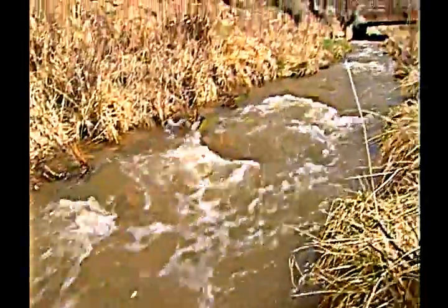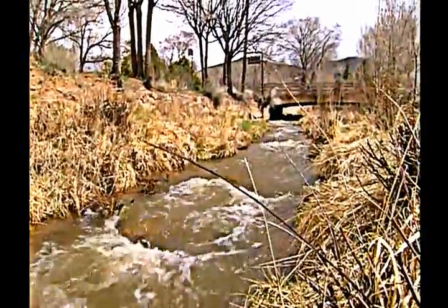Not all the particles that make up turbidity are a public health concern by themselves, but they can protect pathogens against disinfection. Naturally occurring particles, clay and other bits of dirt and stuff, can shield the pathogens from the disinfectant, making the disinfectant less likely to kill the pathogen that you're trying to kill. So it's important to remove turbidity, not just to remove the pathogens, but also to allow the disinfectant to work better.